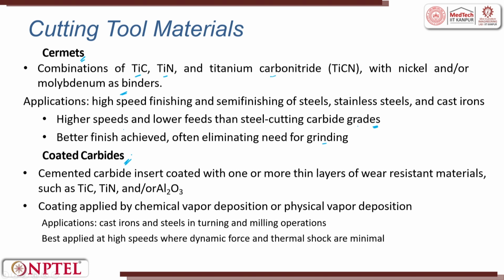When we talk about coated carbide, even if you want to improve the resistance of your insert, we can give a coating. A coating of TiC, TiN or Al2O3 can be given, or multiple layers can be given, such that it enhances the properties. Coating is applied by chemical vapor deposition or by physical vapor deposition, which enhances the tool material property.